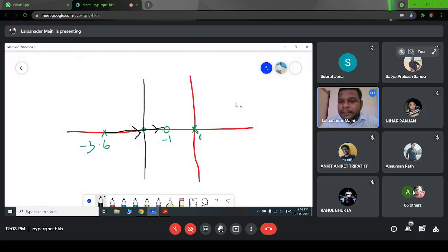So suppose this is 0 and 0. Okay, I am just magnifying this. This is 0 and 0. That means the root locus will start from these two poles also. At the double pole, the root locus branches start, then they will meet at some point and they will break away. So the breakaway point is also 0.